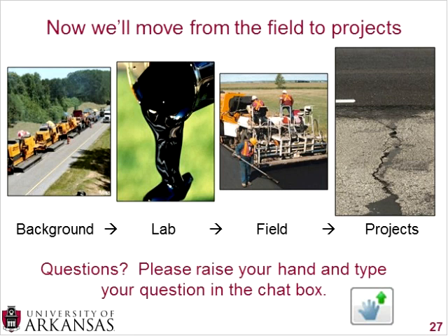So if you're thinking about using this, I would highly advise you to talk to maybe some other state agencies that have a little more experience with this and say, what are some of the key things that we need to really focus on when we're on that job site to make sure that you're going to get that proper ride quality. But I think just like HMA or WMA, as long as you do the proper mix design and you're doing proper construction techniques, you should have absolutely no problem with ride quality. You should see no drop.